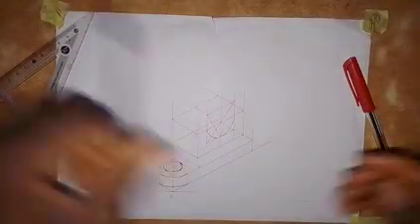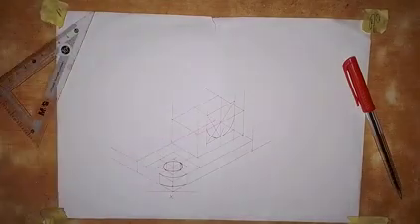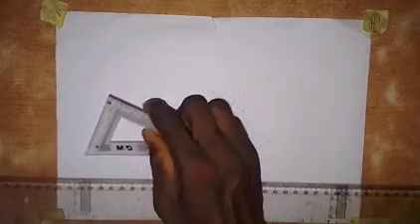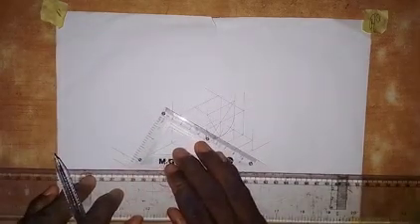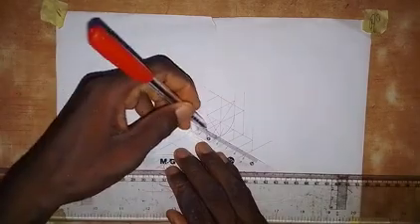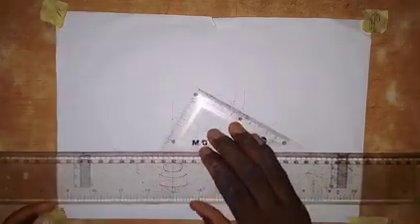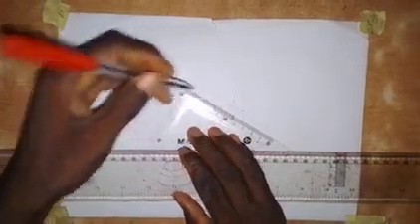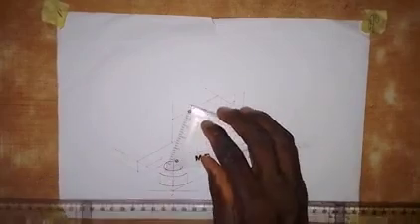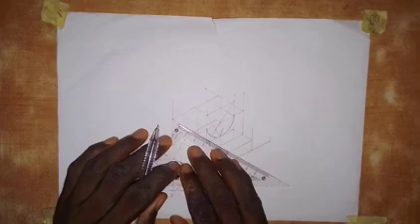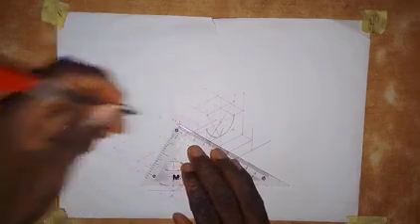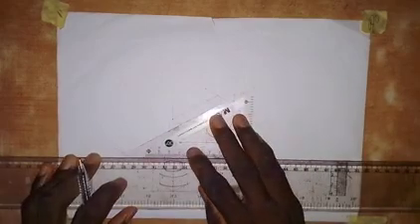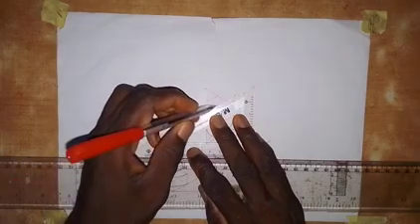So we have to also draw the curve inside it. So what we have to do is, from this point, we draw a line inward, and then here also, we take a line in, then we take a measurement of 20 millimeters from this point. So this is 20. So I will transfer this to the other side. So transfer it to the other side here.